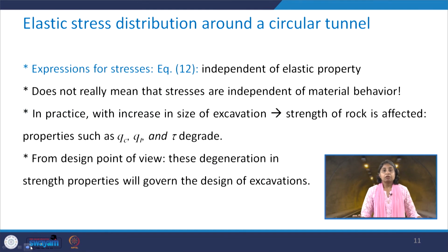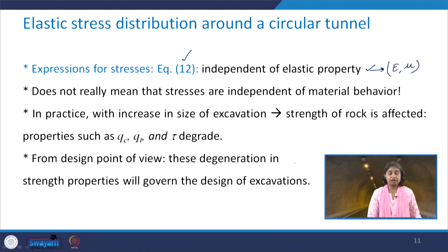Now, the expressions for these stresses, which are given by equation number 12, are independent of the elastic properties, which were E and mu, as we saw earlier. This does not really mean that the stresses are going to be independent of the material behavior.